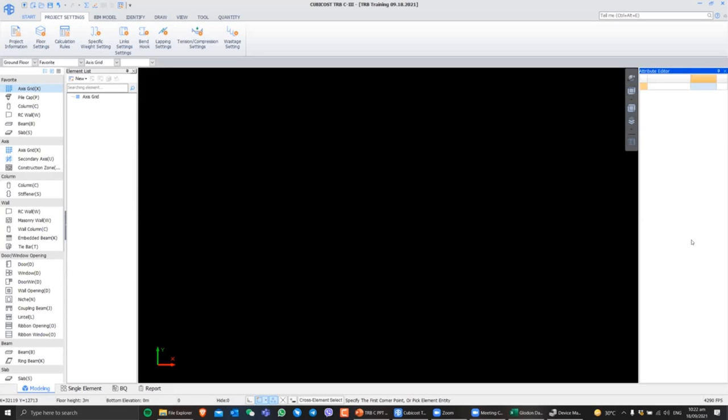Because the process here is, if you model the rebars, okay? You model the rebars, you already preset the calculations. Then the software shows the rebar cutting list. The assumption the software showed, that's it already, no? If you change a small thing, for example, you extended the bar or replaced it, or you changed the location of the lapping, if the software fixes or locks your structure, then once the software locks your structure, you can no longer re-apply the calculation rules. Not unless you reset the ones you did manually.